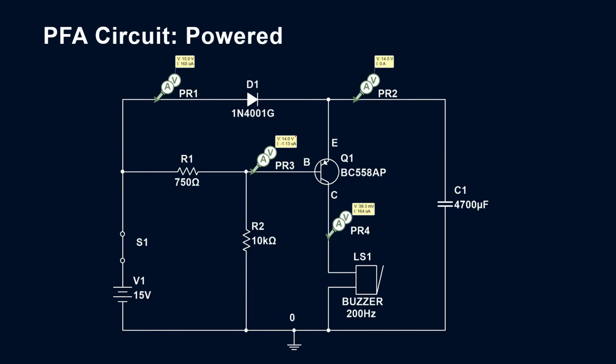So here's our circuit under power, and it's receiving power from this power supply V1. Power comes around to this diode D1, which will be on because we have voltage at the back and no voltage at the front. It will come through here to the capacitor, charging the capacitor, and of course that will complete the circuit back around to the power supply.